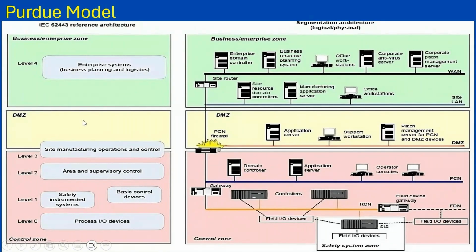However, these interactions happen through high-end deployed firewalls, nowadays the new generation firewalls, which allow the traffic from here. Usually the preferred traffic is unidirectional, one way. Nothing is usually written back here. There are certain applications, for example, advanced process controls or some other applications which need to have some write access, but then there are different mechanisms.